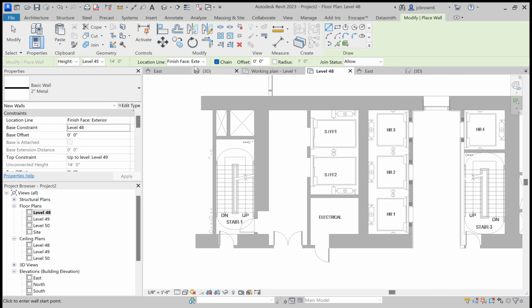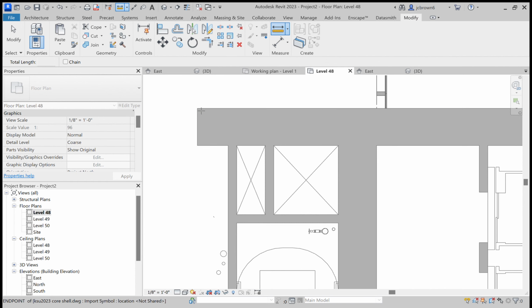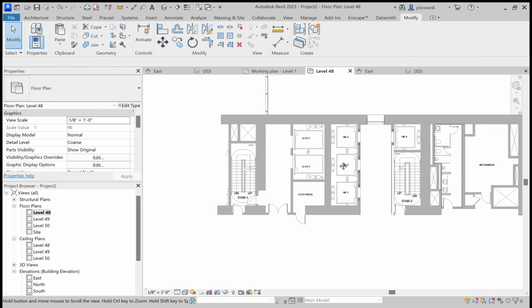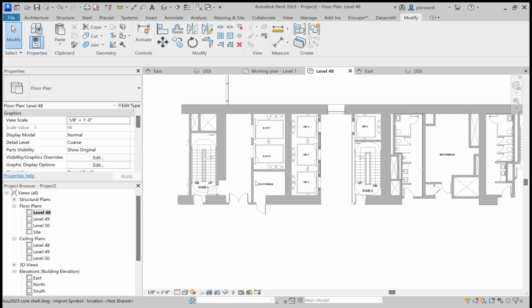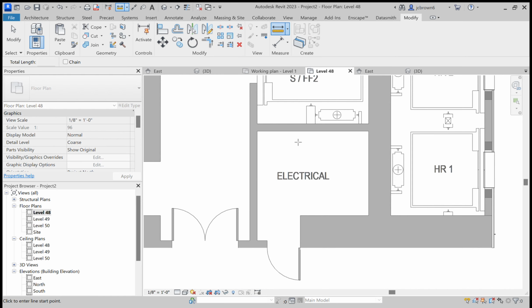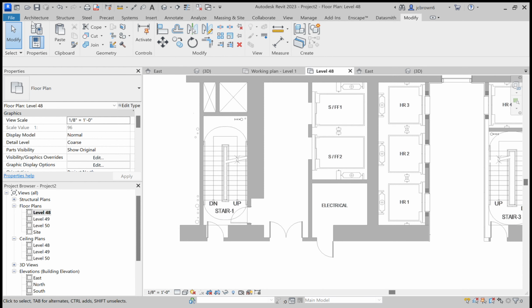And then the wall for your core, all of these walls are a little bit different. So once again, you're going to have to measure this, but they're all going to be concrete. So this is 3 feet wide, and this is 3 feet wide. You also have a 2-foot one here, and then your typical 8-inch, 8-inch CMU, because all of this is concrete CMU.